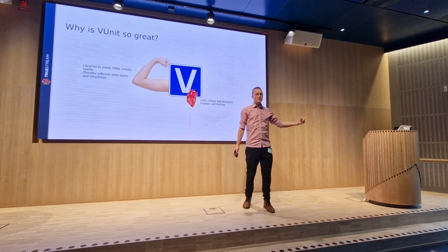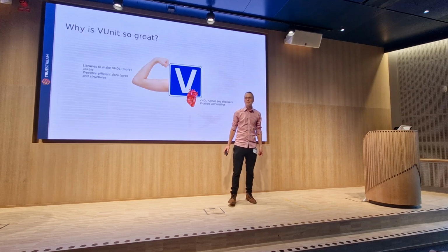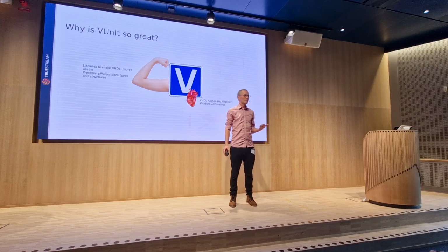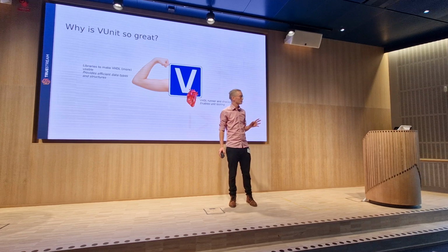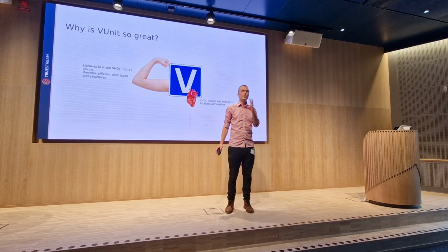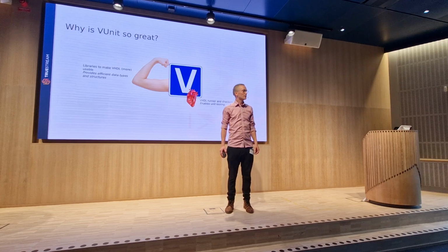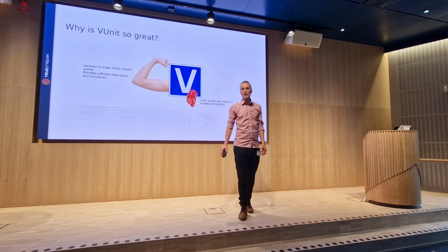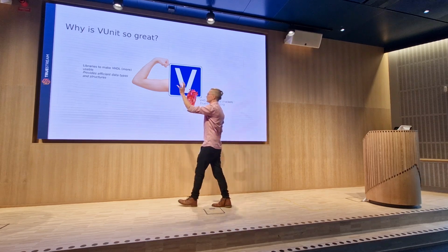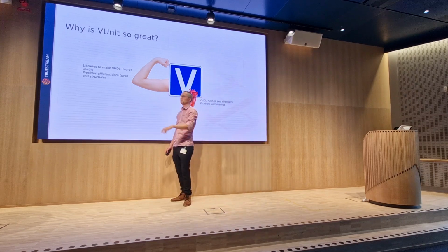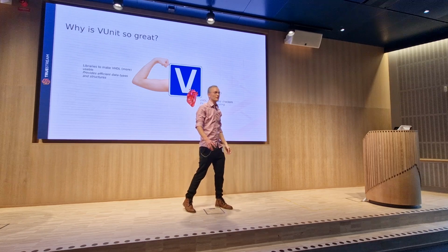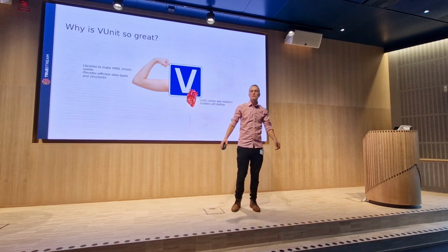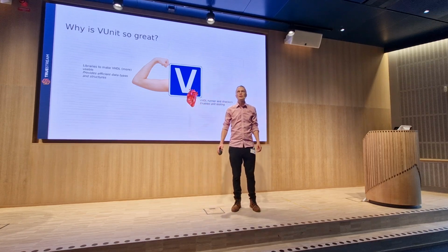And then you have some extra muscles, for example, data types, the array package and the queue package, stuff that you feel like it's missing in VHDL, especially if you come from SystemVerilog. You have the message passing interface, which was the basis for Sebastian's talk earlier. So this really will help you make a much more potent testbench for more advanced and complex systems.